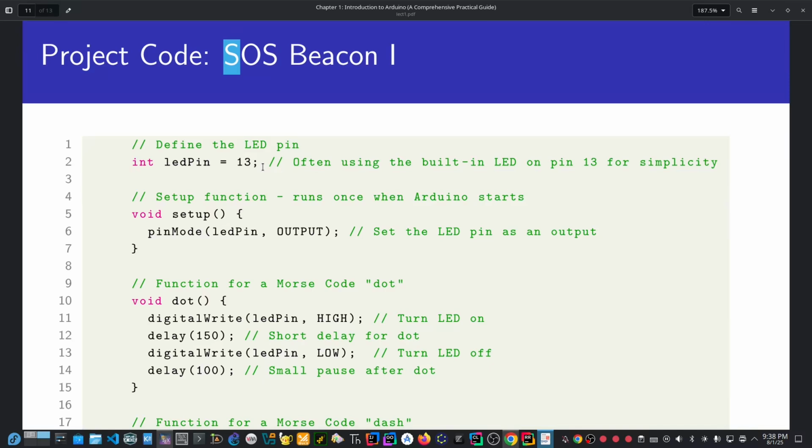Let's also implement it either with the same code or with a different approach to the code. Let's use pin 30 for example here, so we configure our pin. Our pin is a GPIO, so you can use any of the pins since they are GPIOs, general purpose input output. Let's demonstrate with the use of an LED.